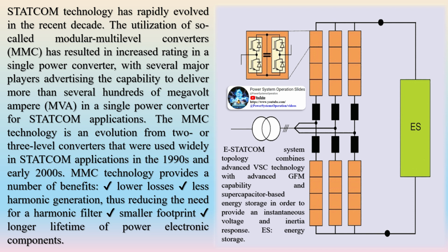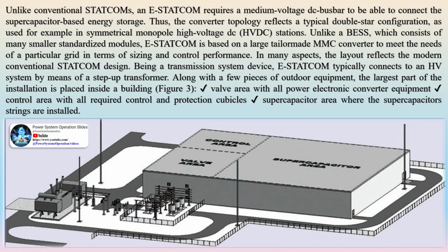Figure illustrates the typical architecture of a STATCOM connected with an ESS to an electric utility system. The static synchronous compensator (STATCOM) is a shunt-connected, power electronic converter-based FACTS device. Unlike the static VAR compensator (SVC), the STATCOM does not use capacitor or reactor banks to produce reactive power. A major disadvantage of a traditional STATCOM without energy storage is its limited steady-state operating modes, which are either inductive lagging or capacitive leading. Although the traditional STATCOM can control both output voltage magnitude and phase angle, these cannot be independently adjusted in steady state due to the lack of significant active power capability.